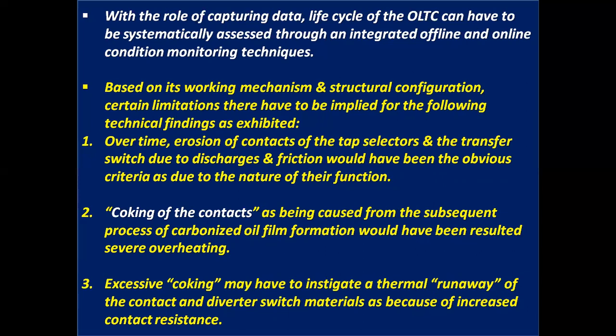Over time, erosion of the contacts of the tap selectors and the transfer switch due to discharges and friction would be the obvious criteria, due to the nature of their function.